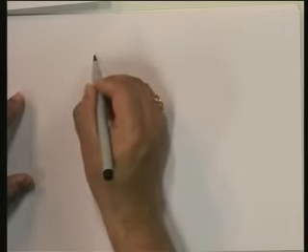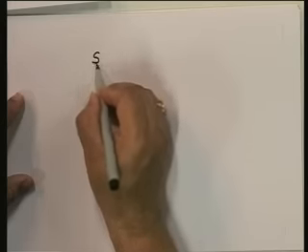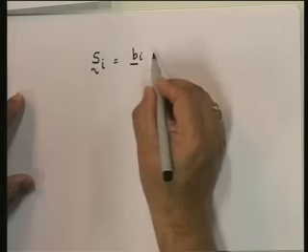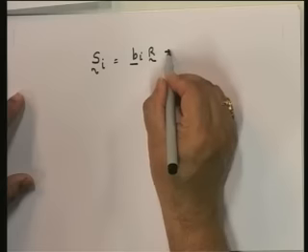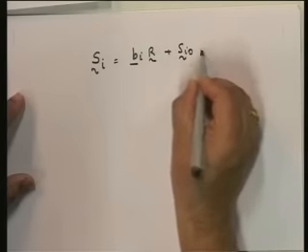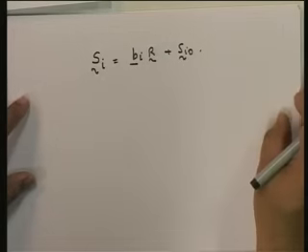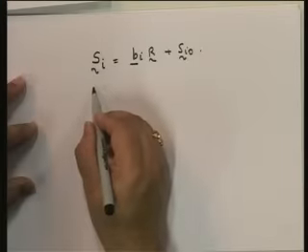what would you do? You would find out Si is equal to Bi into R plus Si0. Understand that once I accept that X1 is a redundant load, it behaves exactly like an external load. The only problem with X1 is that whereas for most other situations we know the loads, here X1 is a load which we do not know. So here I can write it in this fashion.